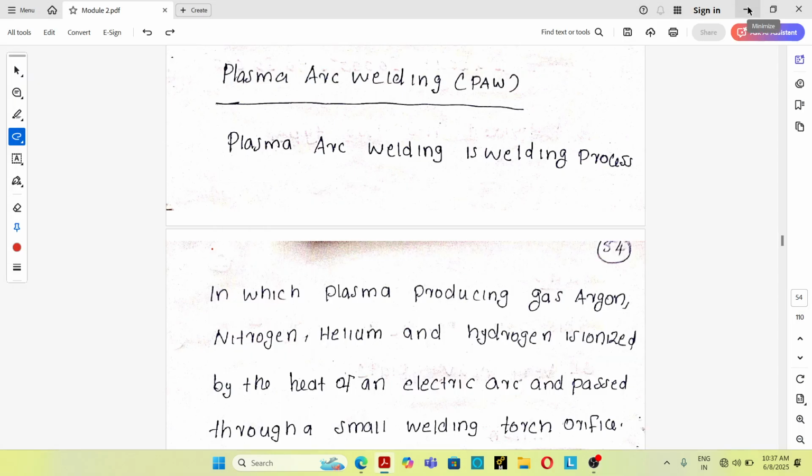In this video, I am going to discuss the plasma arc welding process. The short form is PAW process. Plasma arc welding is a process in which plasma producing gases like argon, helium, nitrogen and hydrogen are ionized by the heat of an electric arc and passed through a small welding torch orifice.